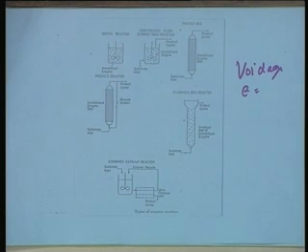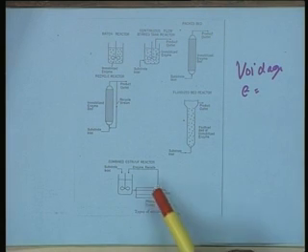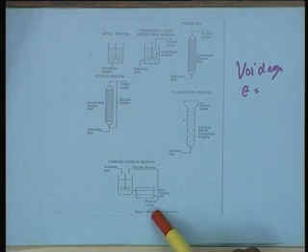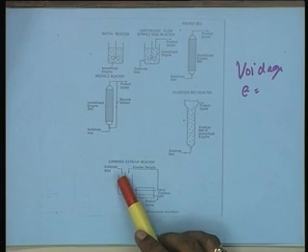In the case of soluble enzyme, with the use of plug flow reactor you will drive away the enzyme simultaneously and you cannot use it continuously. Now, in the case of a CSTR you can use a soluble enzyme along with a soluble or insoluble substrate by carrying out in a CSTR and coupling the CSTR with the ultrafiltration module. That is, the reactor output, instead of going directly to the product stream, passes through an ultrafiltration unit in which the product stream is filtered out and can be taken out as a product stream, while the retentate which contains mainly our enzyme is recycled back into the reactor.